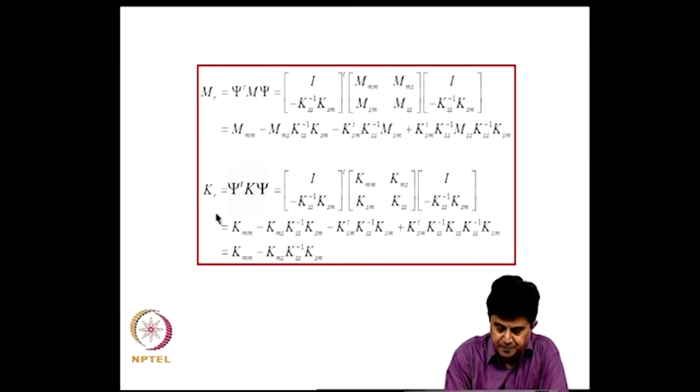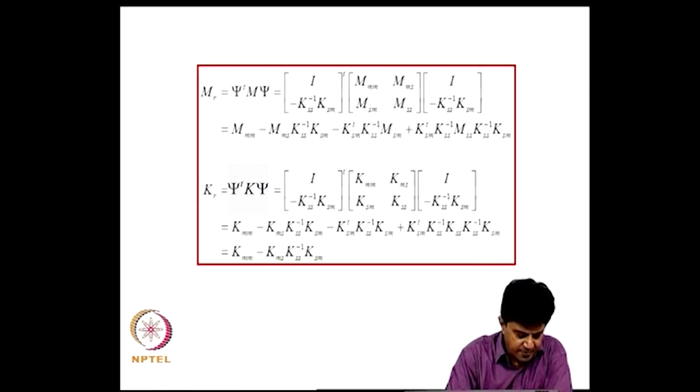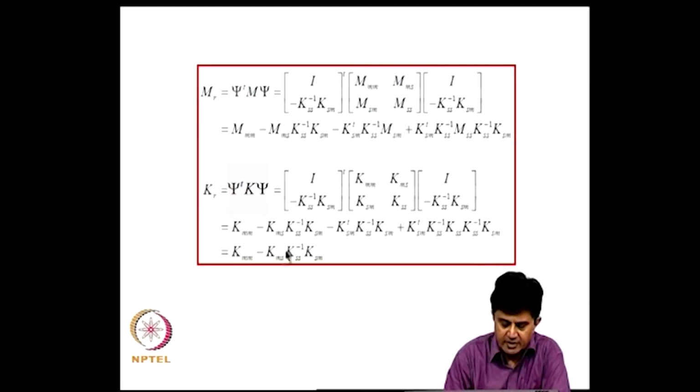Similarly, the reduced stiffness matrix is psi transpose k psi, and by rearranging the terms I get this as the reduced stiffness matrix.